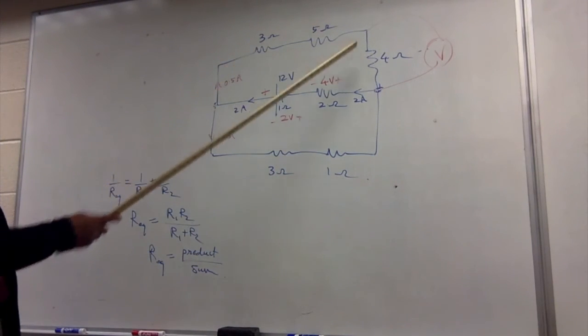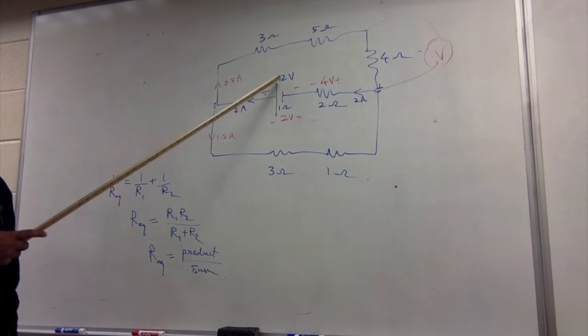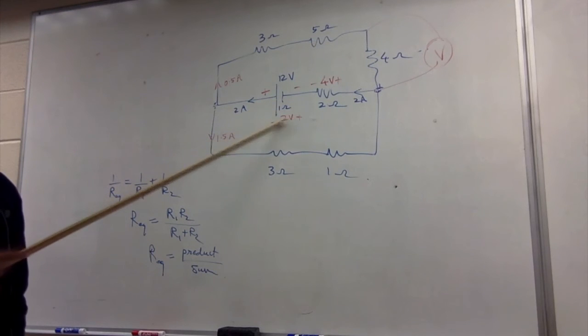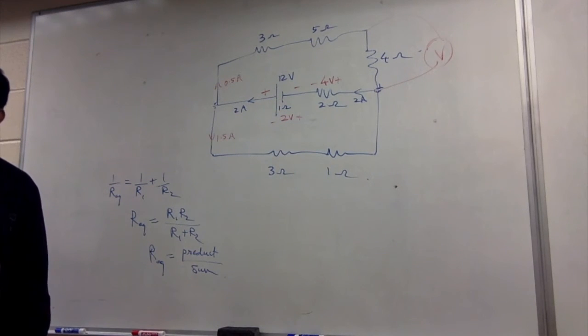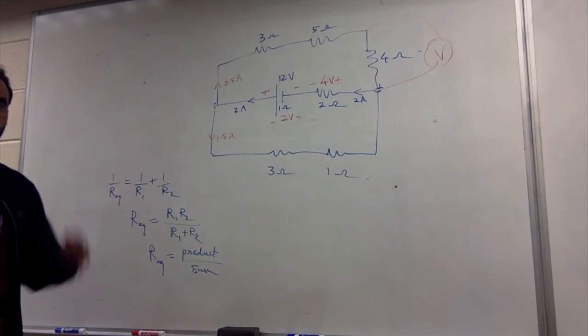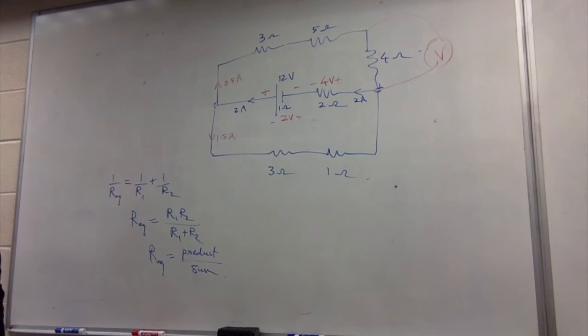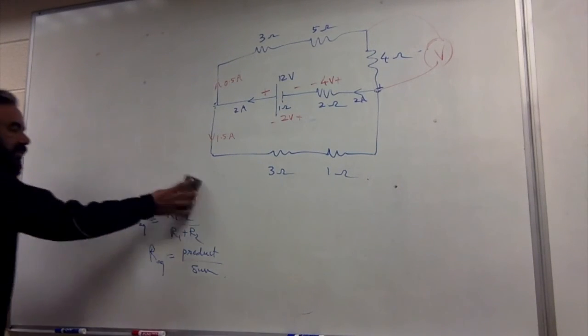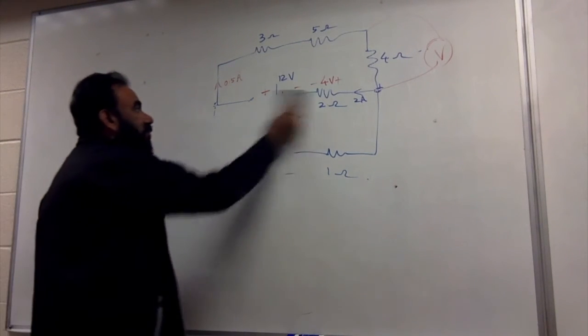It could be one of these resistors is wrong. It could be the cell's EMF is wrong. It could be the cell is very old, so it's no more 1 ohm, it's like 10 ohms. You know, it could be multiple factors causing this voltage not to be 2. Yeah, so you can explore the entire circuit with the help of simple rules.